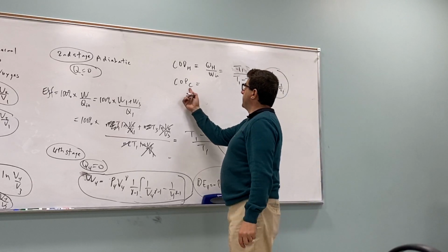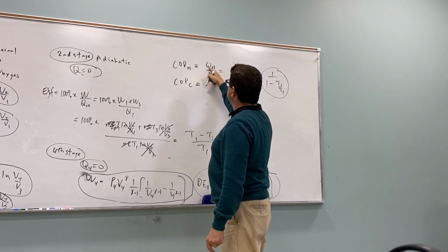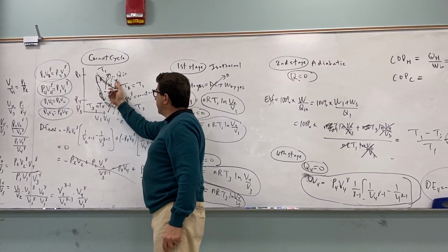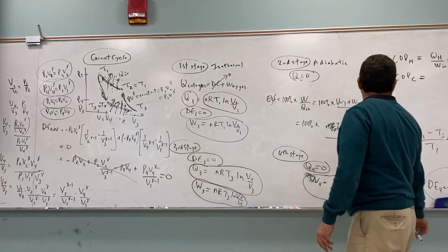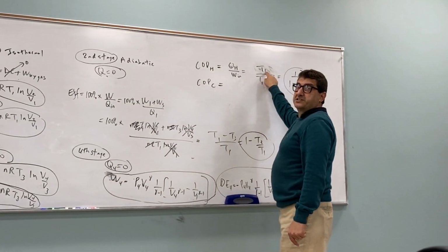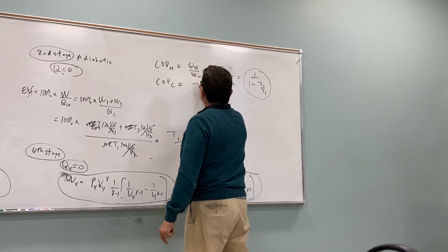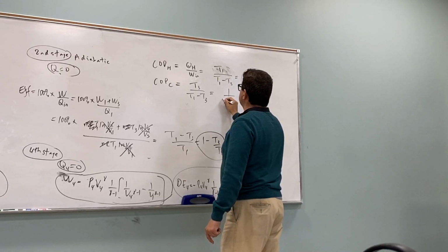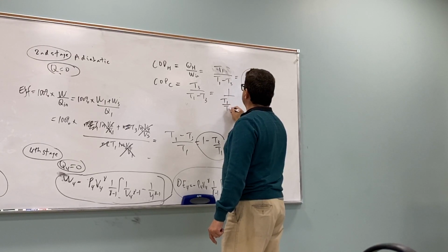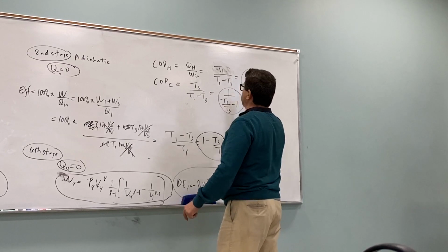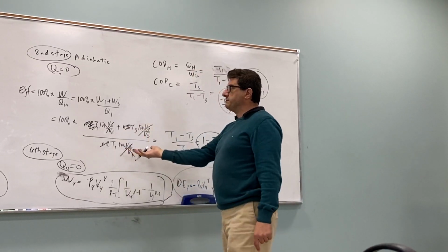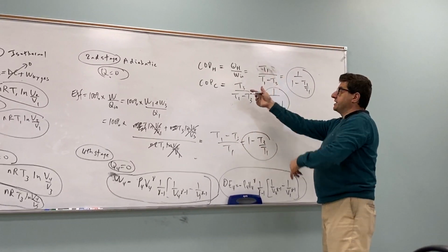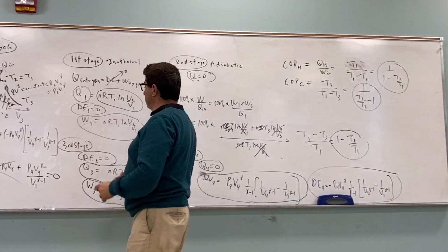Okay, how about coefficient of performance in the cold? The difference with that one is, that one you're using this heat, not that heat. So I believe the only difference is that here is T3. Okay, so this is the coefficient. So you could take the same efficiency that you got for the engine, reciprocate it, and then get the equivalent coefficient of performance in the heating mode.